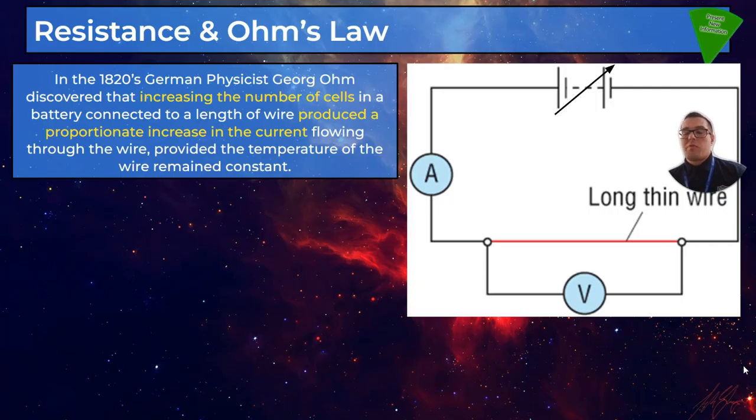And in this topic, there are basically two practicals you will mainly be focused on, but they can both be summarised very similarly in terms of the circuit diagram. So you can see one example of a suitable circuit diagram here. In this case, we have a variable power supply, some electrical component we're investigating, in this case a wire, and in order to investigate it, we must connect our ammeter in series and our voltmeter in parallel.